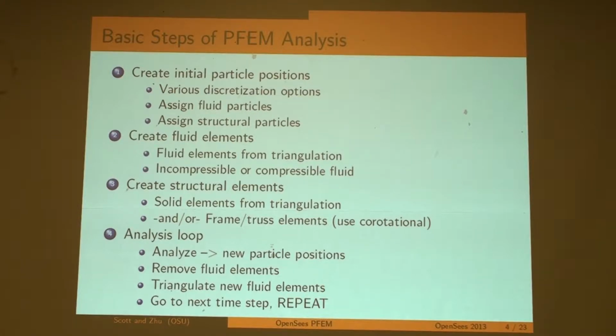And then we triangulate the fluid domain, create fluid elements for incompressible or compressible fluids, and then create structural elements from triangulation. We do solid elements or frame elements, as I'll show in an example. So we can mix frame elements with fluid loading fairly easily with this PFEM approach.